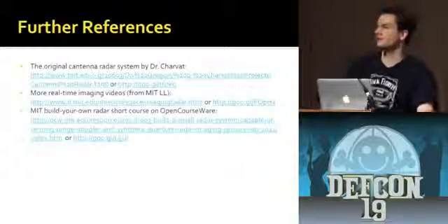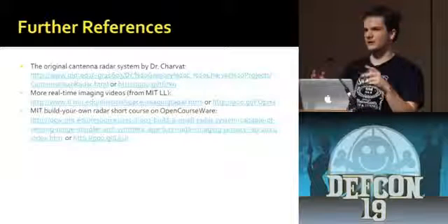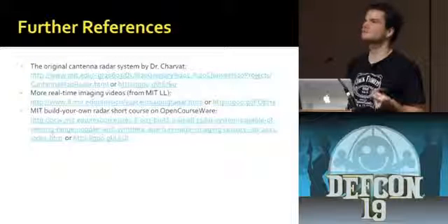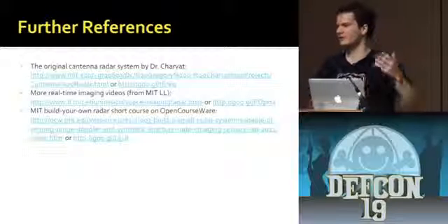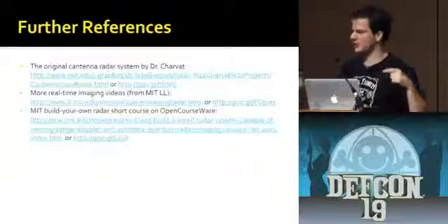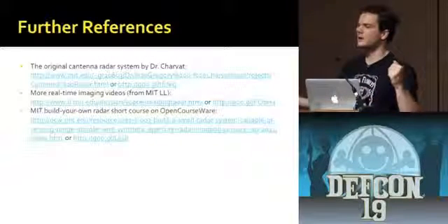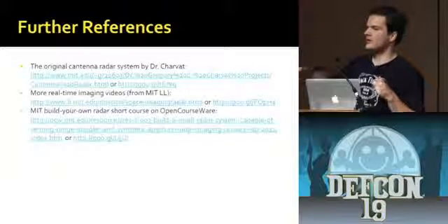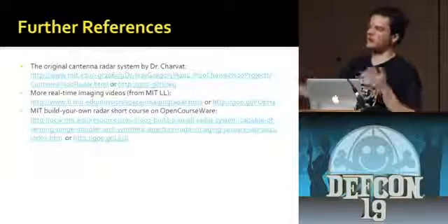Is the Doppler effect from a fast-moving object enough to mess up your position measurement? That kind of depends on what you're trying to do. If you're trying to measure something moving really fast, on the order of a plane or something, you might have some impact. When I was talking about it before, I said that something moving 3 meters per second, which is like a person walking really quickly or a slow jog, is producing a 24 hertz signal. At the chirp rates I was dealing with, I think 10 meters corresponded to like 667 hertz.